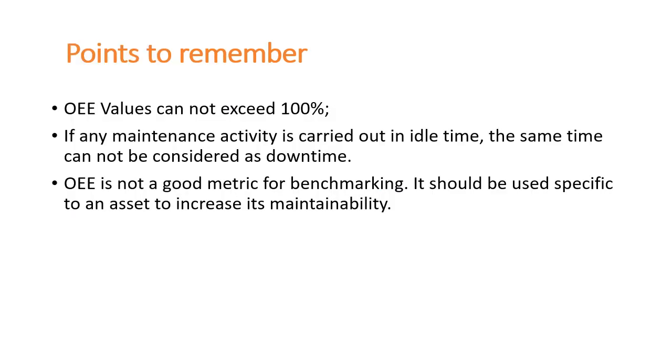Some points we should remember while calculating OEE, because OEE percentage is a better measure of a specific equipment. You cannot compare if you have a machine A and a machine B, or the same machine A in some plant and in some other plant. You cannot compare the OEE value directly, because this gives us some wrong calculation.